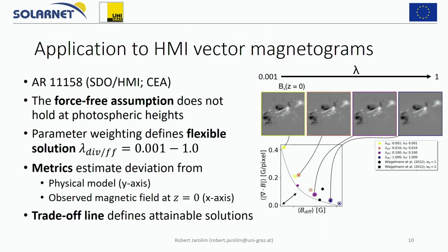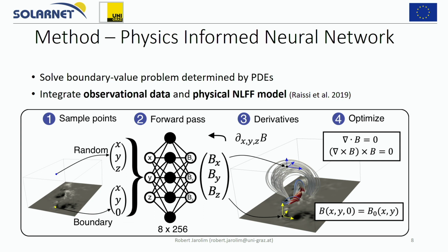So when we go back to this one here, all of the way that this works is by just sampling points. And in the end, we don't have a mesh. For the entire simulation, everything is incorporated in terms of these X, Y, and Z coordinates. So we have no underlying mesh, basically. It's just a different way of sampling the data points, and having a higher resolution is not strictly beneficial here. So we can go lower in resolution, but it also doesn't change our computing time. Only the result could change if we use a higher resolution. But it's just the amount of data points that we are sampling.